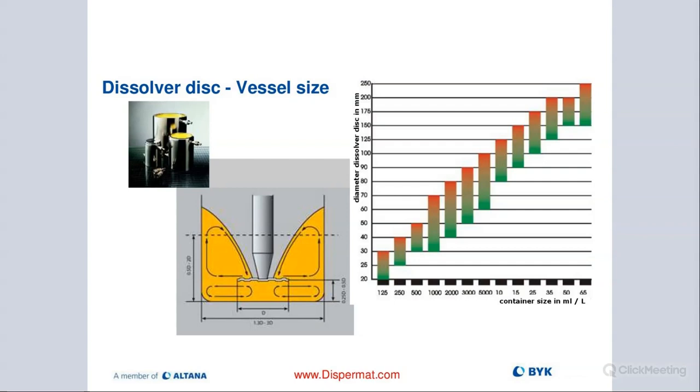Just briefly, for this pre-dispersing, it's really critical the vessel size. The 1/3 diameter ratio to vessel diameter still holds true today. So basically, you can see that on this graph right here. Try that the blade diameter is about 1/3 of your vessel, then you're optimizing the ratio. Of course, depending on the viscosity of your material, that can vary.